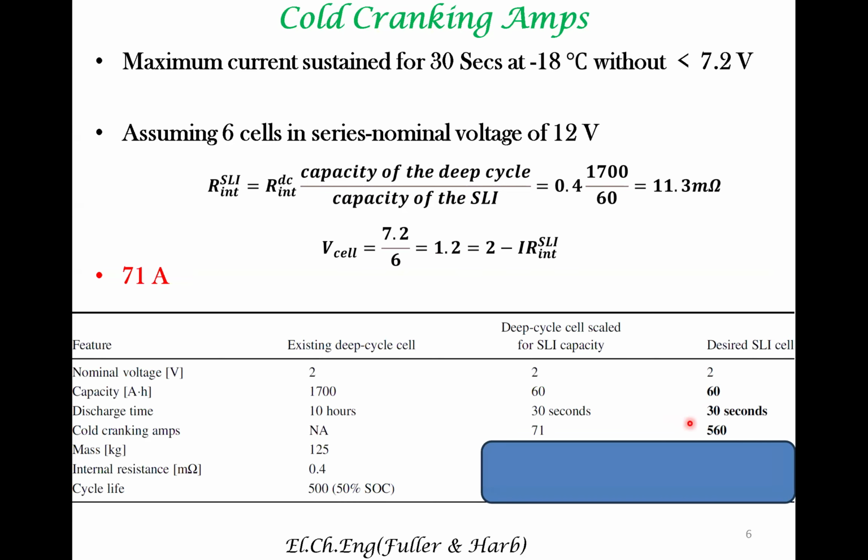However, this is what you obtain. That is not by the design specification. We need much higher cold cranking amps, which the desired cold cranking amps is about 560 amperes. So what do we need to do?